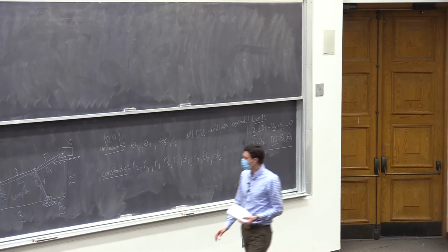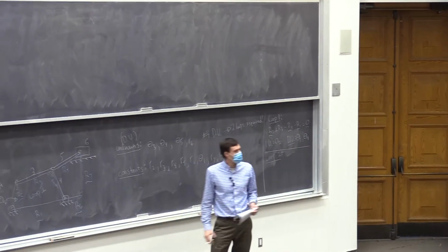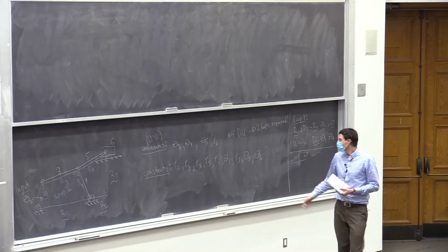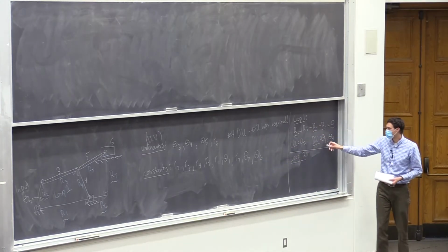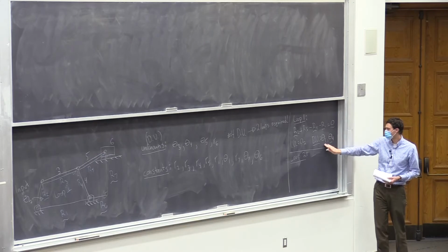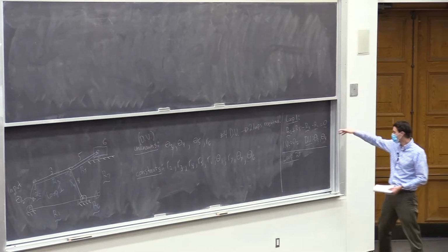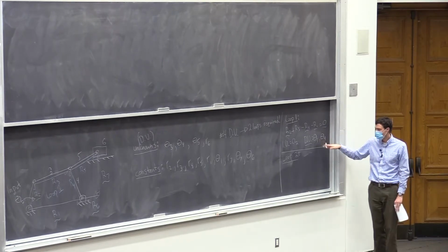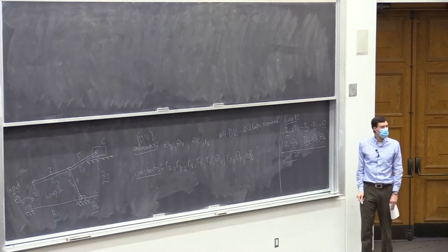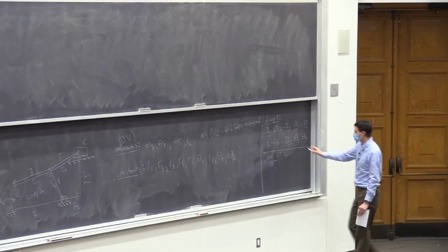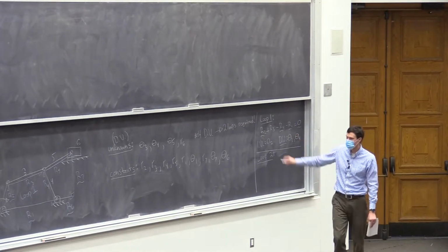On loop 2, we actually have some options. And the key is loop 1 has some outputs, right? Theta 3 and theta 4. Those are like the outputs. That's what you solve for in loop 1. And you can solve loop 1 on its own and calculate those. And one of those should become the input to your loop 2. One of the outputs from your first one should be an input to the second one.